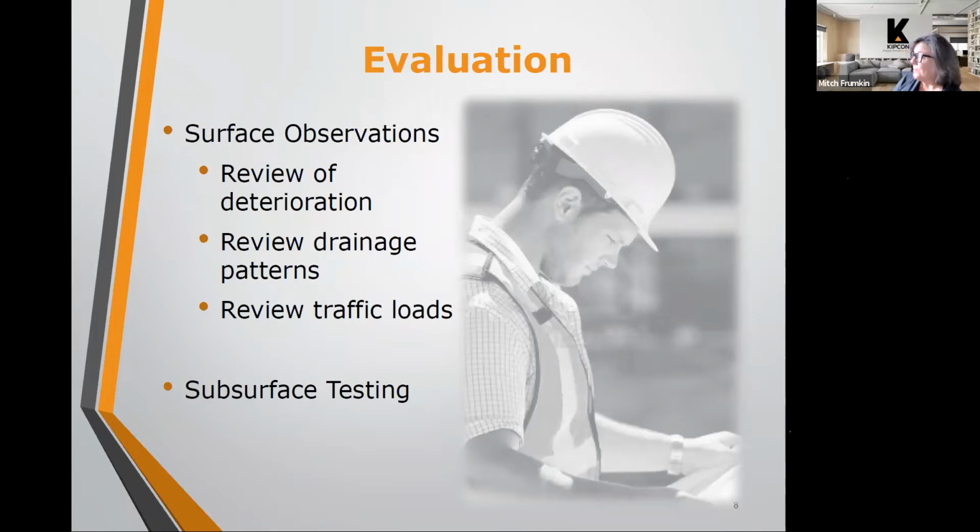Another thing we also like to review with the community is where the traffic loads are, meaning when refuse removal trucks come in, they are very, very heavy trucks, and they can often do damage to the pavement. We often see a lot of damage in front of dumpster pads. There are methods of remediation that we can use in those high traffic load areas that can strengthen or reinforce the pavement a bit so that you get a longer life out of it.